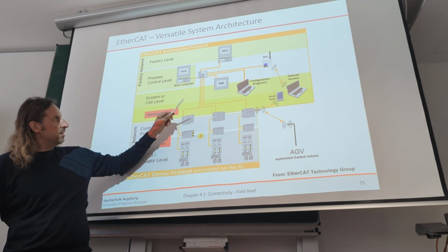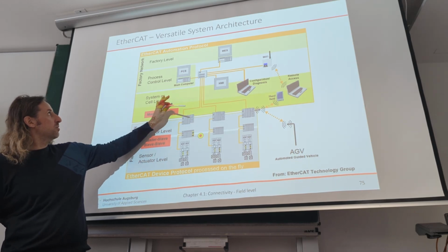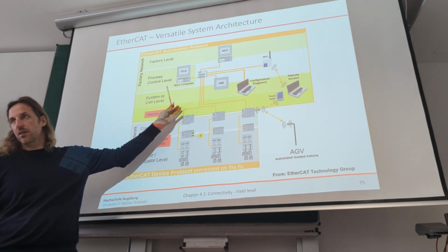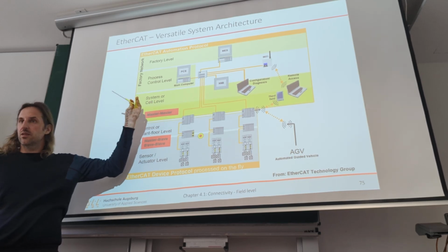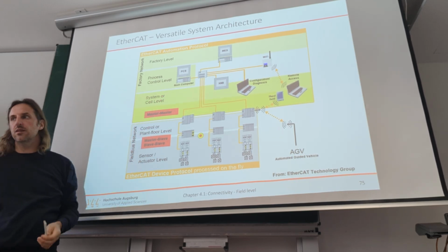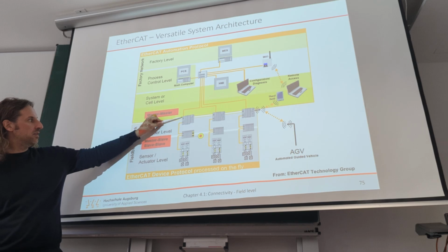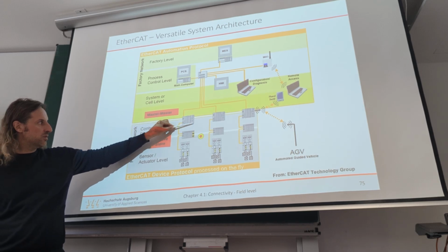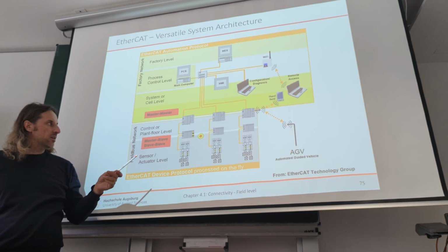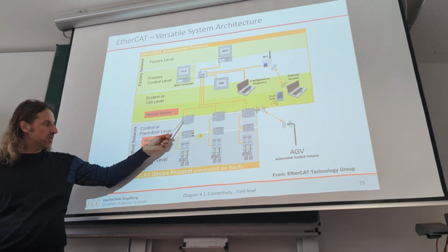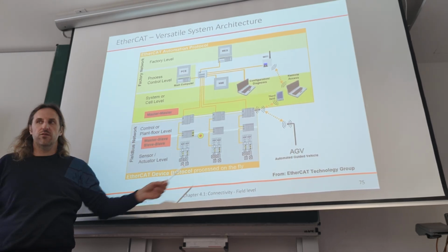And that's why they created a kind of flexible protocol where they use normal Ethernet frames on the higher level. And then at some point they switch from the normal Ethernet, which is not real-time capable, to this processing on the fly.